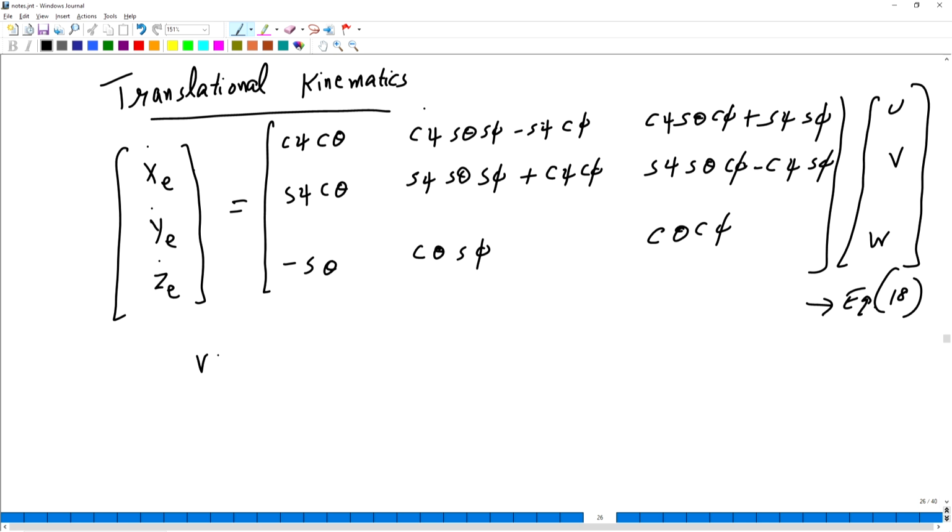Now the 3 degree of freedom block considers the motion in the longitudinal xz plane. Here we have side velocity v equals to 0, rates p equals to r equals to 0, bank angle phi equals to xi equals to 0, and side force is 0.